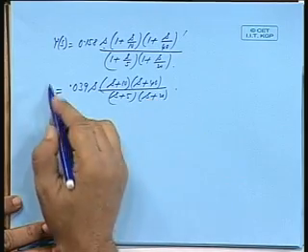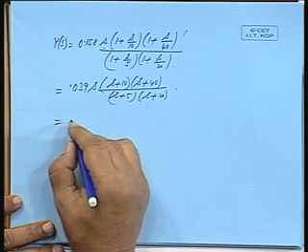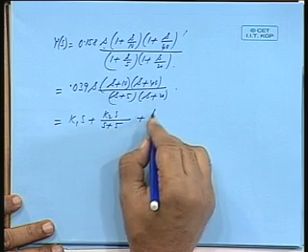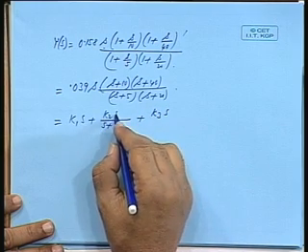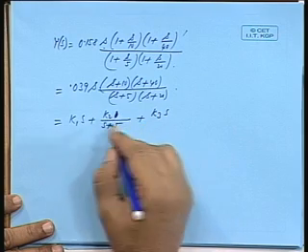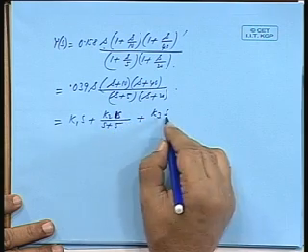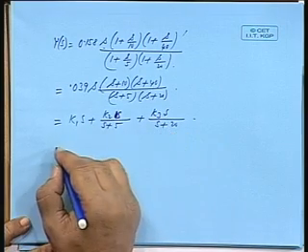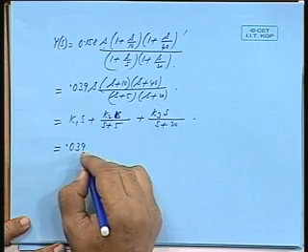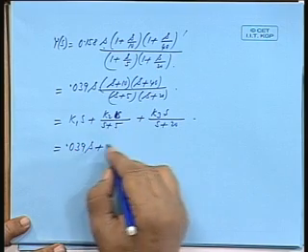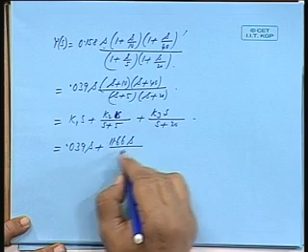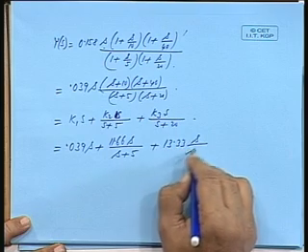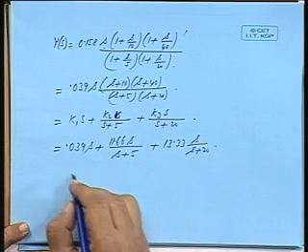If I Foster 2 means you break up Ys. So, it is k1 into s plus k2 into s by s plus 5 plus k3 into s by s plus 20, which is an admittance function. So, that turns out to be 0.039 s by the usual method of partial fractions, 11.66 s by s plus 5 plus 13.33 into s by s plus 20. Correct me if I am wrong.